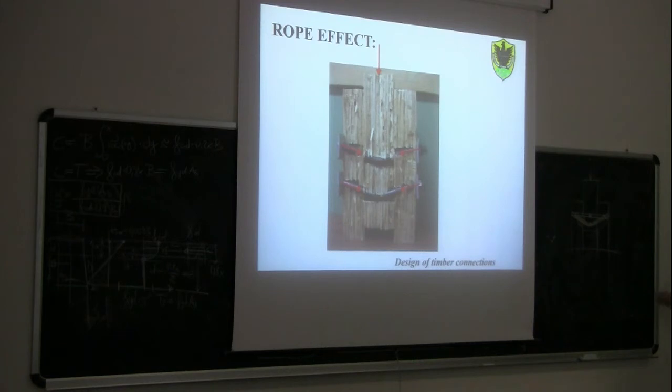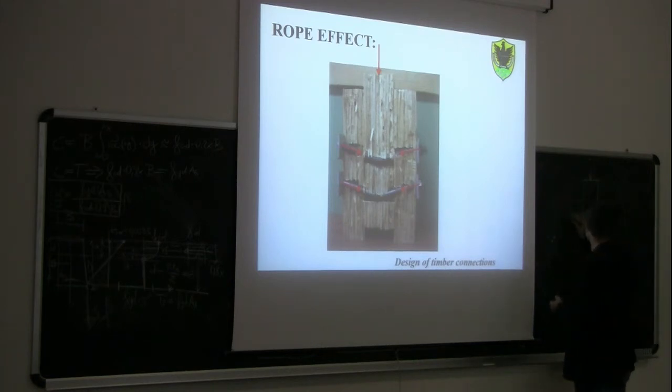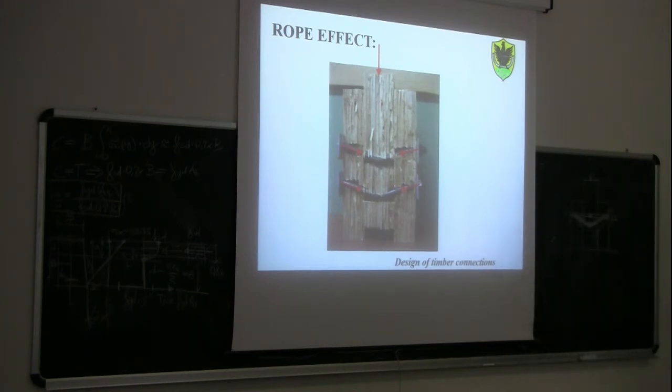Now, if we redo the same test, but using these plates here, what is going to change? So if this dowel now has two plates here, and we start loading, and then the dowel forms this plastic hinge. What can we expect in this case, as a difference to the case that we have just discussed? The length, yes, the length of the dowel would like to increase.